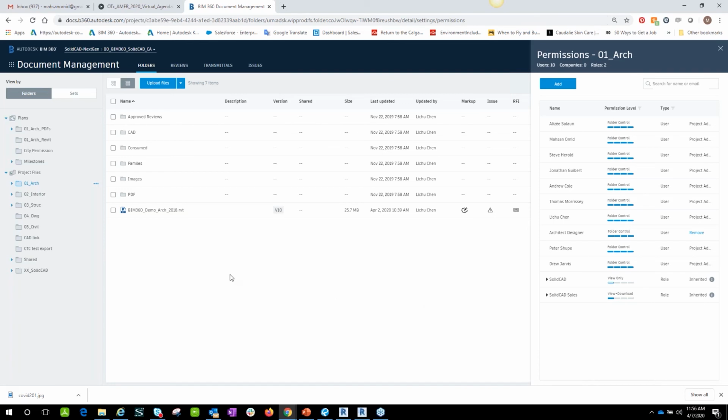Also, Anthony's asked another question here, and it's really about Revit versions and how that fits into BIM 360. So his question is, if he's using Revit 2017.2, how does using BIM 360 differ? And the answer to that is it's actually sort of an older legacy platform with older versions called Collaboration for Revit. When you buy BIM 360 Design, you are granted access to that, but all the features we're going over are really specific to what's called BIM 360 Next Gen, which works for Revit 2018.3 to present. Excellent. Thank you very much, Ian.